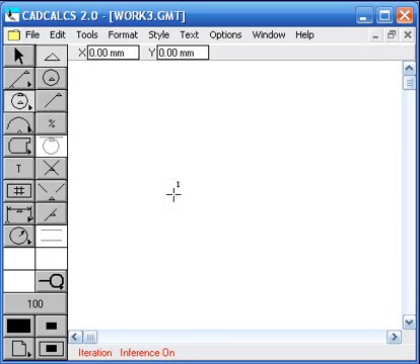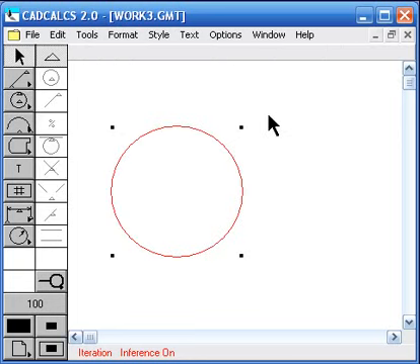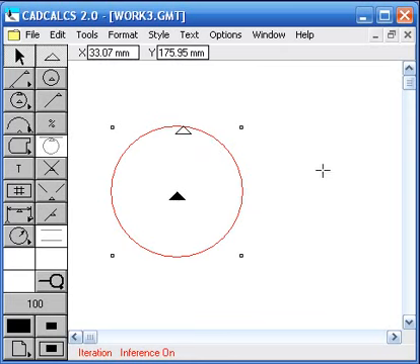This one here is the first option, probably the most commonly used option. It's called the center and radius circle. So the first point defines the center, and the second point defines the radius point. When you open the circle, you'll see this is where the center was. You can control the x and y coordinates of this center point, or you can constrain it using a geometric constraint. And this shows a point on periphery which controls the x and y coordinates of this point, and the current radius and the diameter.